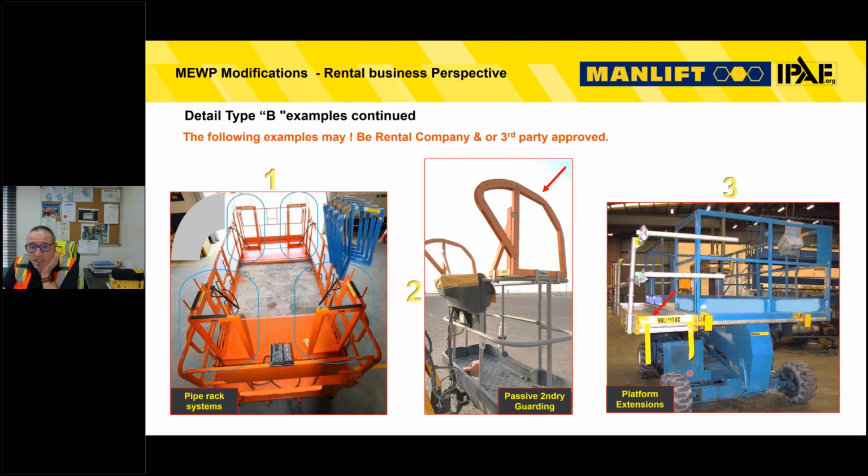Okay, some more type B. We can see pipe racks again for a scissor lift. Again, done correctly, it's quite okay, or not, if it's not done correctly. Here we have some third-party approved, what we call secondary guarding, static secondary guarding applied to the handrails. It's called passive secondary guarding, to protect against entrapment. Again, if you use a supplier that's looked at the design calculations and made sure they're not being detrimental to the MEWP's operation, then that can be done safely, or not.